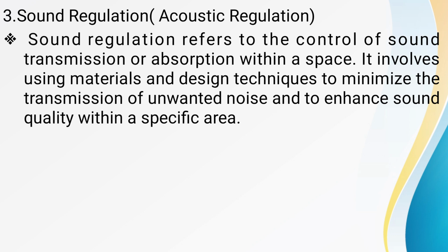Especially in structures such as concert halls. And we also have sound insulation, whereby materials with high density and mass, like concrete or also gypsum board, can block sound transmission. We also have sound reflectance, whereby we have some materials that can reflect sound. Hence, they are useful for creating specific acoustic environments.